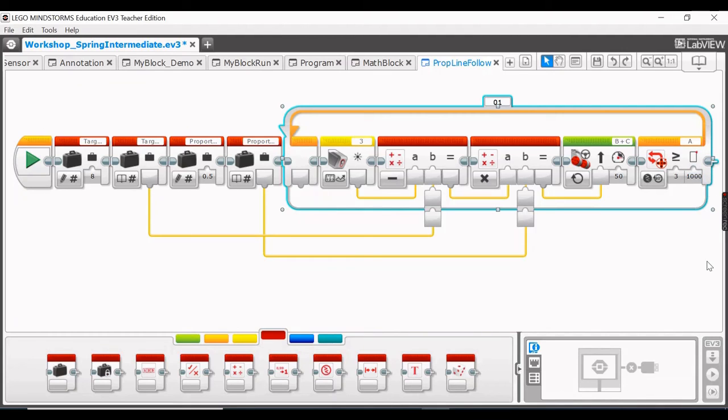And if the motor is not even moving, theoretically this loop will keep going on and on until you decide to stop it. I'd also recommend keeping speed, especially for specific operations, not above 20. And yeah, proportion 0.5, 0.75, target value, I recommend keeping it at a solid 50.